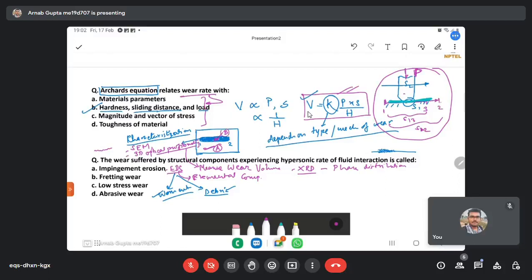Generally, surface A, we can say that, it can have higher corrosion resistance than surface B, or it can be the other way around also. Like if some oxide phase is forming at B and it is forming a passive layer on top, then its corrosion resistance may increase. You never know that. So as a result, we can see a lot of synergistic parameters or happenings are involved here.